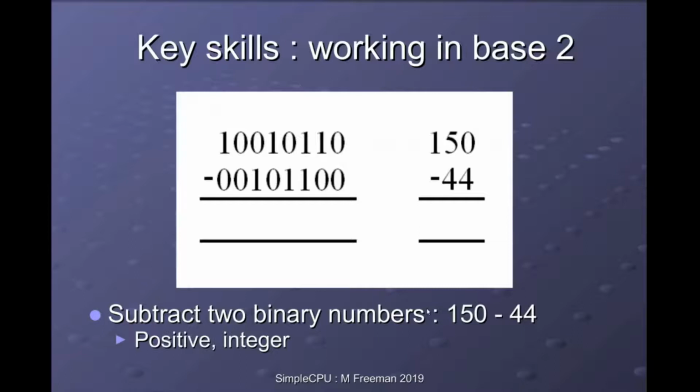So subtraction. Well, first, before we understand what hardware we need, we understand what process we have to go through for subtraction. Again, some people struggle with binary subtraction, they get confused, but just think, how would I do it in decimal? And it's exactly the same process. So we'll start with this example. 0 take away 0 gives me 0, 1 take away 0 gives me a 1, 1 take away 1 gives me a 0, 0 take away 1 I can't do, so I have to borrow from the next digit as you would in decimal.